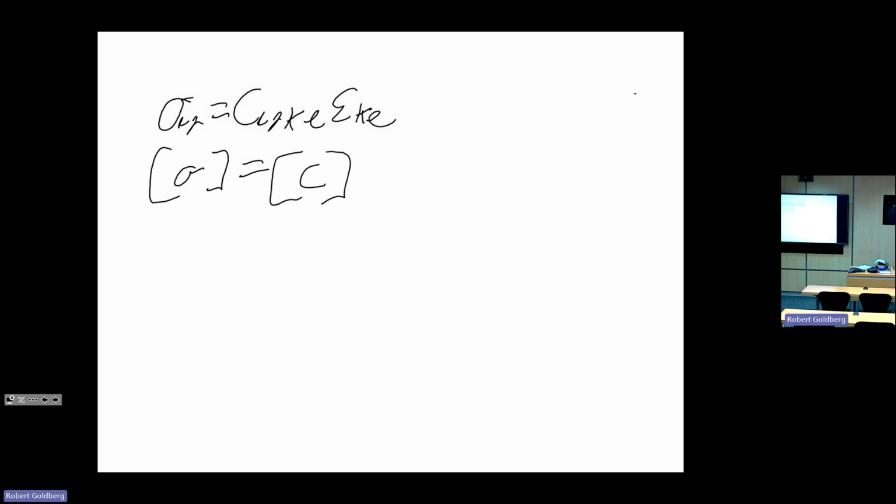So for an elastic material, the relationship between stresses and strains can be defined as a linear relationship. Using our formal tensor notation, we can say that sigma ij is equal to Cijkl times epsilon kl, or sigma is equal to C, which is called the stiffness matrix, multiplied by the strains. And Cijkl is a fourth order tensor which defines the stiffness matrix.